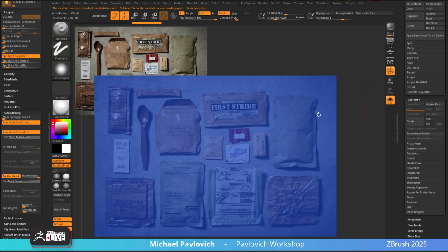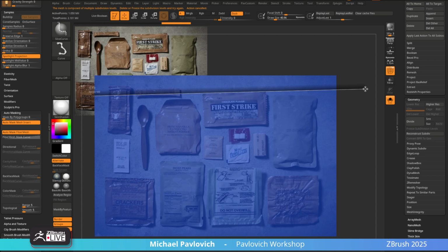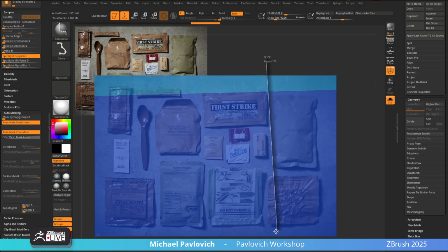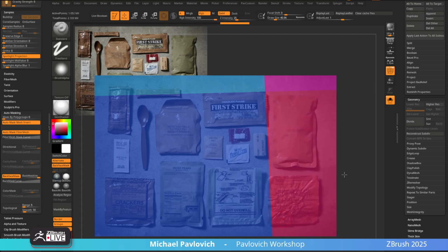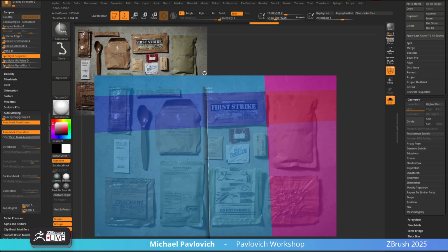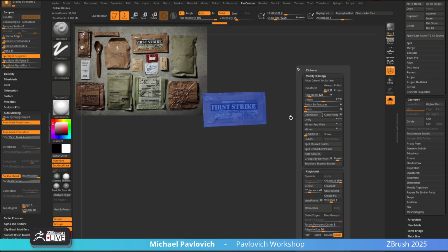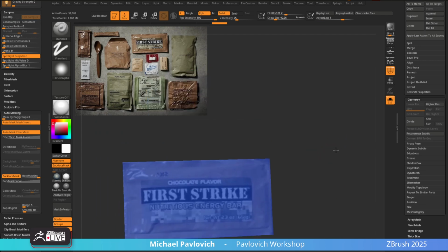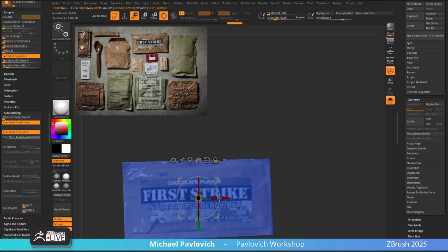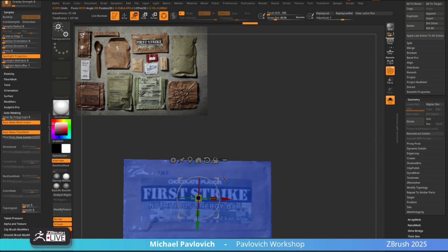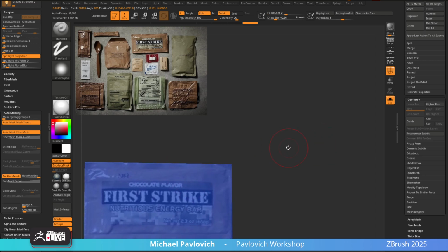Oop, first we got to say delete lower. We don't need subdivisions, we just need geometry. I'm going to say U, and U. Control Shift Tab, Geometry, Modify Topology, delete hidden. And then if you want to straighten this out, just hit W. I like to use these little safe action bars, and then we can just use this to kind of eyeball this so that it's basically flat.